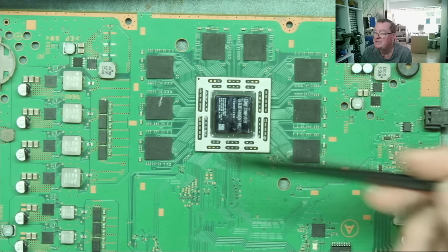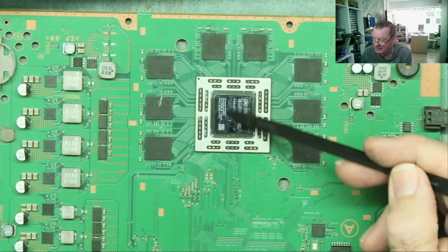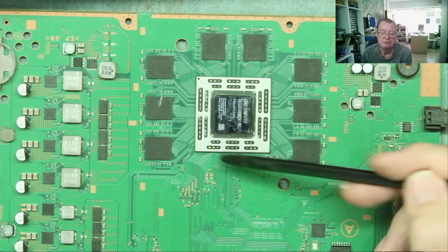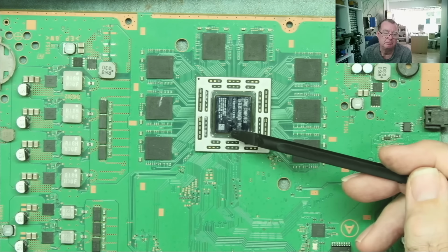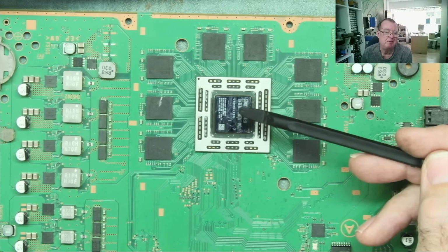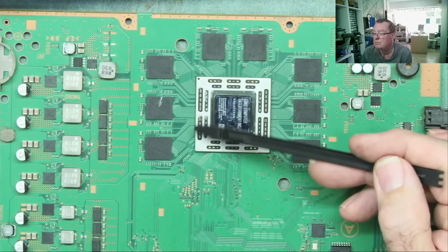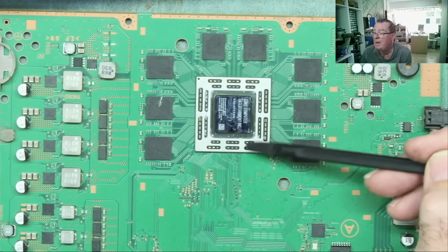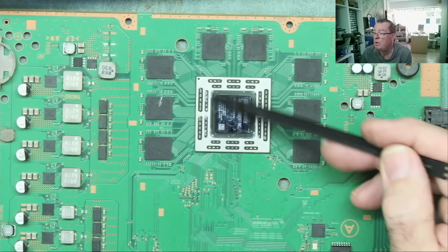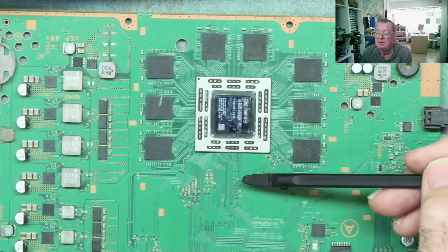So the thing is heating up and cooling down, heating up and cooling down. Maybe you don't have a good heatsink compound, it's dried out, so it's heating up even more and heating up faster and cooling down faster because it's not attached to the heatsink properly, which has thermal mass. These sort of failures, again, cause the same sort of stress. So the metalwork and the PCB will heat up and cool down at different rates, which means they will expand and contract at different rates, and that can fracture the connections, okay, the balls.